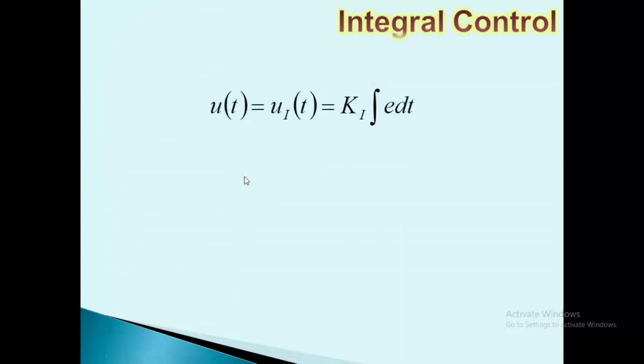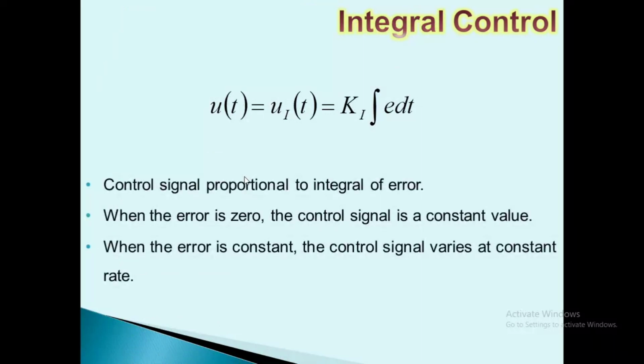Then applications: it can be used in conjunction with your P control, it can't be used alone. Now integral control. What is the control signal of integral control? The control signal of integral control is proportional to the integral of error. These things are very important to understand.